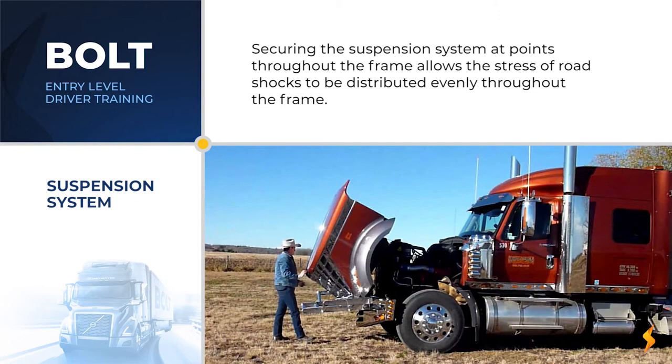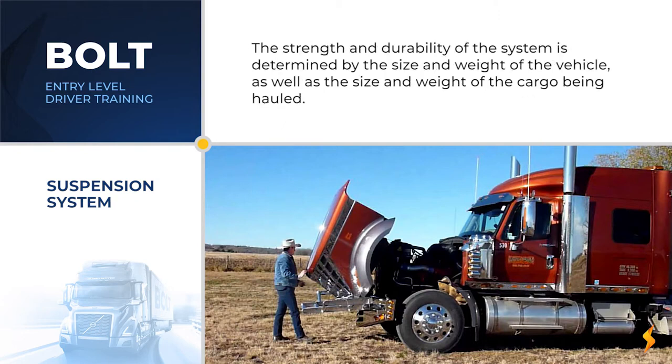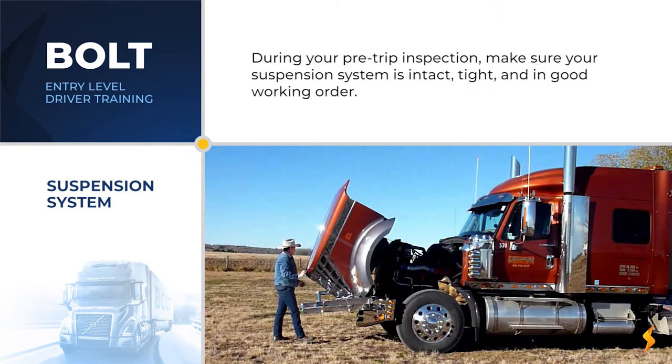Securing the suspension system at points spread throughout the frame allows the stress of road shocks to be distributed evenly throughout the frame. The strength and durability of the system is determined by the size and weight of the vehicle, as well as the size and weight of the cargo being hauled. During your pre-trip inspection, ensure the suspension is intact, tight, and in good working order.